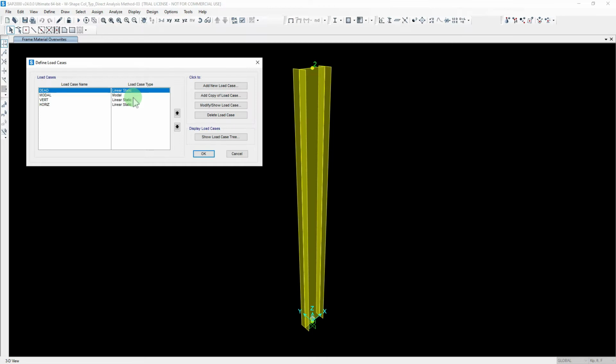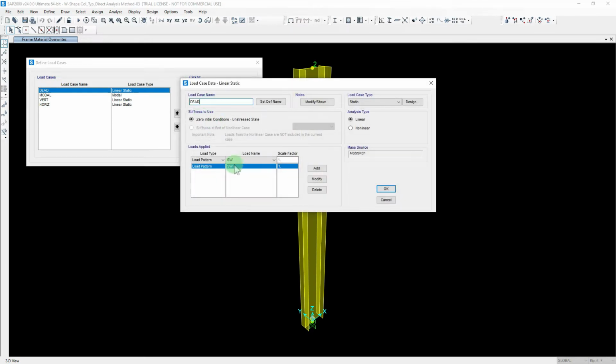Okay, so here again you can see that the load case is named dead. Even though I modified it to self-weight, it didn't change it because this is the default of a load case. It was created as a dead load case automatically by SAP. Here I'm going to modify that. I want dead, like I said, to represent self-weight. You see, it's showing self-weight down here, and I wanted to match it as a name. Self-weight. Again, we'll keep it as a linear analysis. Say OK.